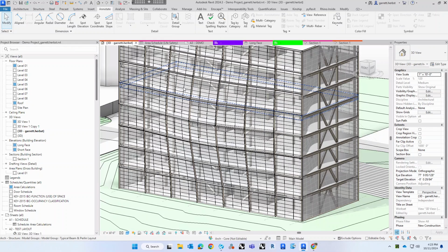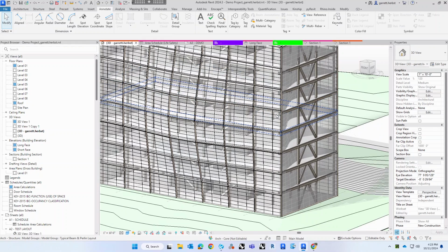One detail that I put in here relates to the direction of the CLT. The CLT is not meant to be cut, but it can be cut in the short direction. So right now, the nice little side detail that Kevin really liked: that floor slab is currently horizontal. In the other model, it was following the mast. What I did was straighten that out.